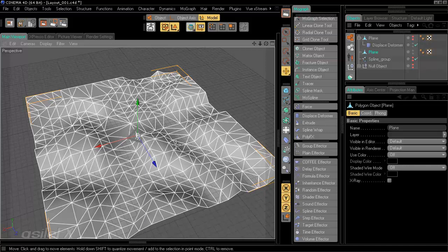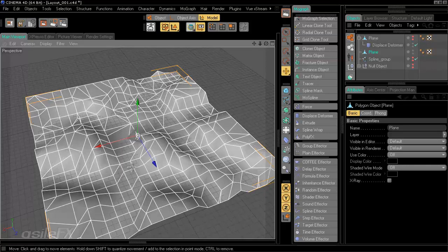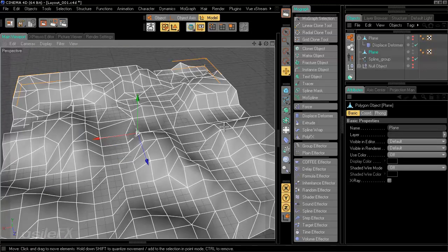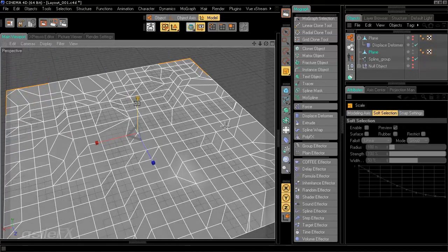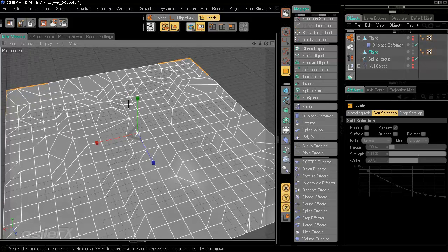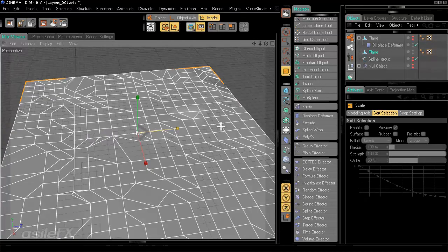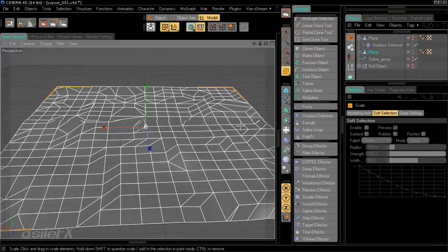We can then untriangulate this again, but turn off Create N-gons and set the angle to 90. If I switch to the scale mode, we can squish this down, and we see a very different grid than we had before. That gives us some nice variations.